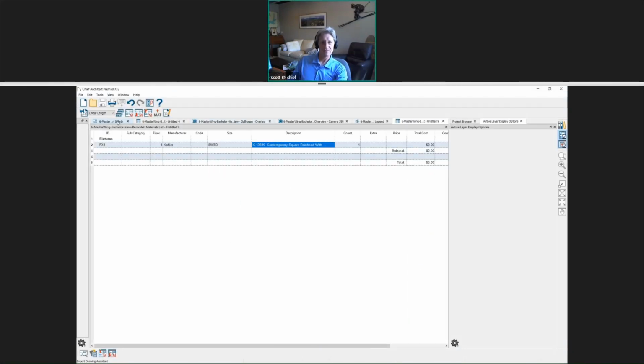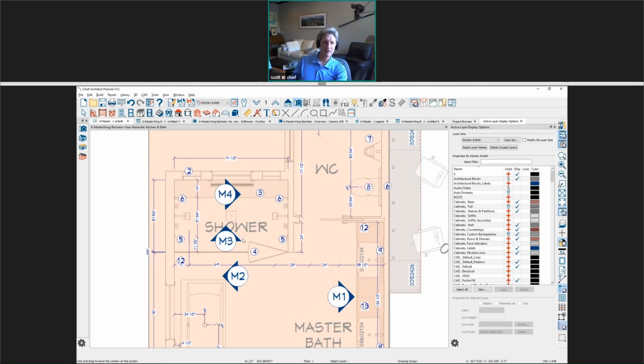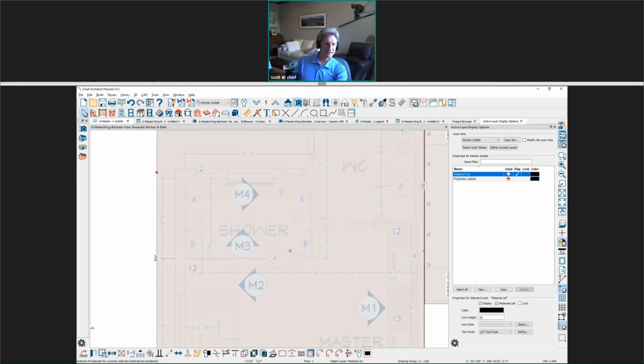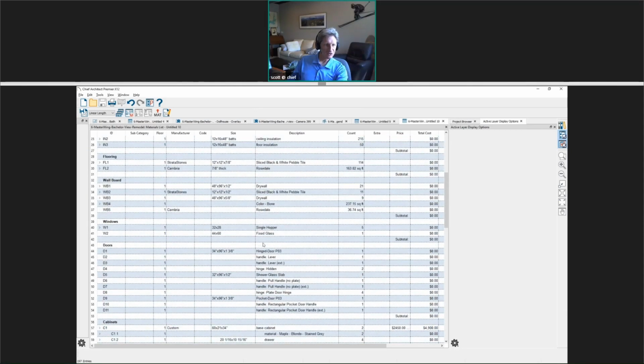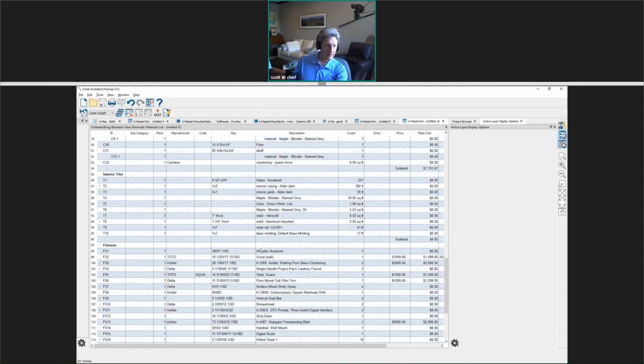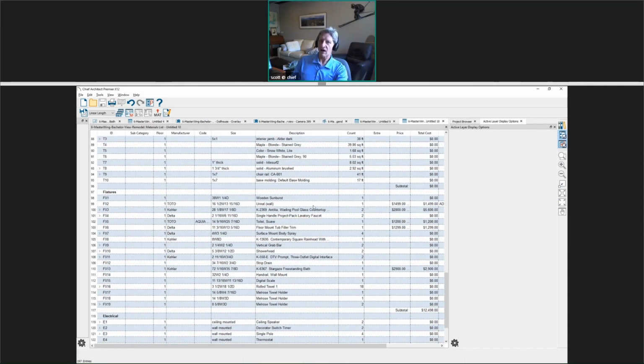Sure. And let's just take a look. Let's generate it just for fixtures. So let's click on this guy. Let's open up a new materials list. Let's come down to the fixture category. So you want to go line item by line item. And if we come down here, here's a urinal, right? Right. Let's give it a little more screen.